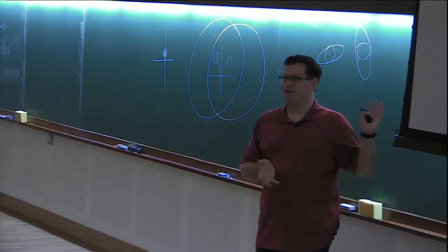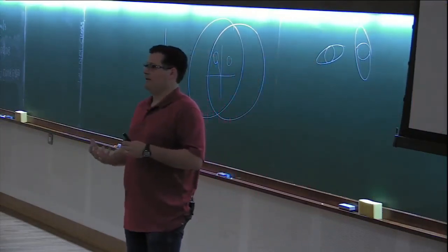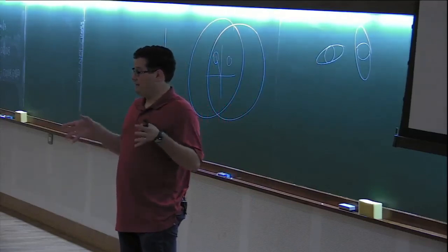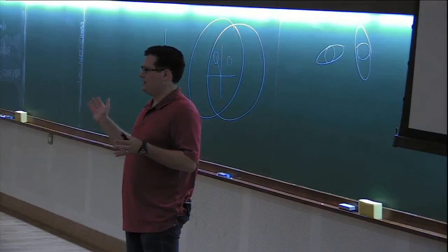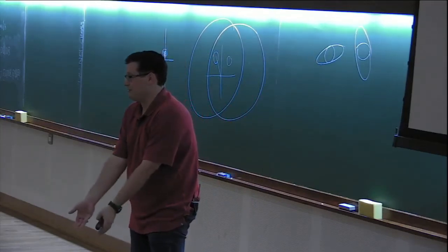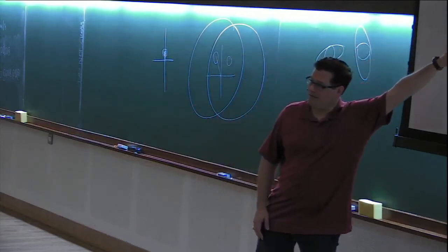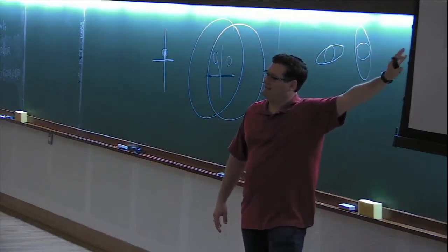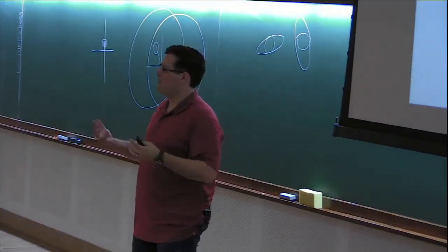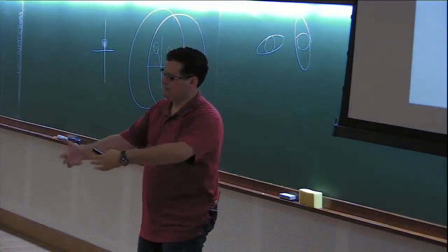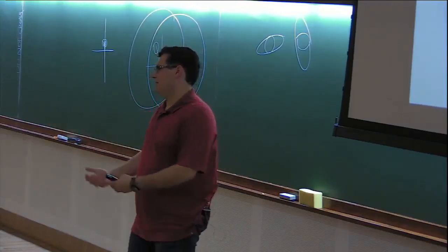I see. And for instance, VJ has a recent publication where I think he's doing 3 or 4 qubits that way. The problem they run into, A, is, like I said, they have limited bandwidth, and B, they have limited dynamic range. So first, it's hard to fit them all in, and then when you do, if you read out 4, it'll just saturate. This is something we're actively working on, and I'll talk a bit on Monday. There are more sophisticated parametric interactions, more mode amplifiers. It's a little bit harder to pump them. Let's say you invest a little bit more in the amplifier hardware, but now you could handle 10 or 20 qubits per amplifier, then it's a net win.